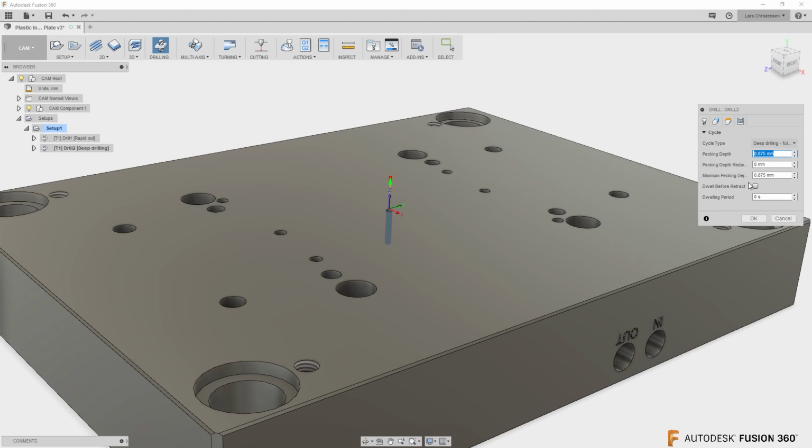Somebody, please feel free to add to that in the comment area. But I have always done either just the diameter of the drill or the diameter of the drill times 1.5, kind of depending on how brave I have been. But I think that's just how I've always done it, and I don't know. I don't think it was something I read.